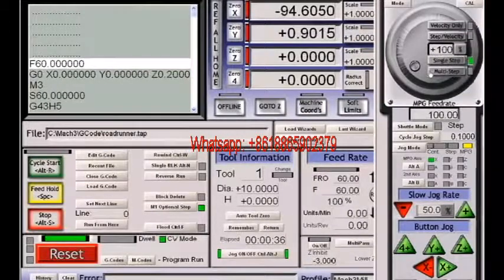Single step mode will move you one single step whenever you rotate the wheel a small amount. You must stop between steps to get single step to work. Multi-step, you don't need to stop. You can calibrate your MPG wheel: rotate it 5 clicks, and the axis will move an appropriate amount for those 5 clicks of movement.